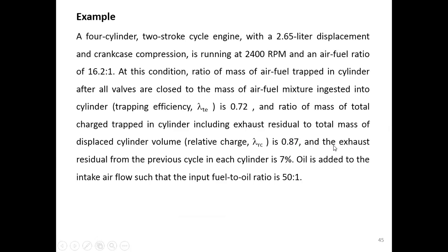And now they talk about the exhaust residue. They give you the information that the exhaust residue from the previous cycle in each cylinder is 7%. Oil is added to the intake airflow such that the input fuel to oil ratio is 50:1.